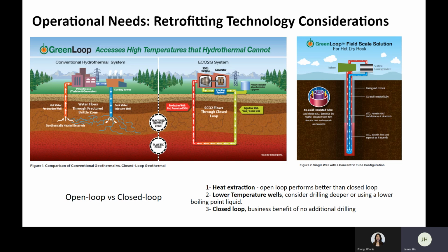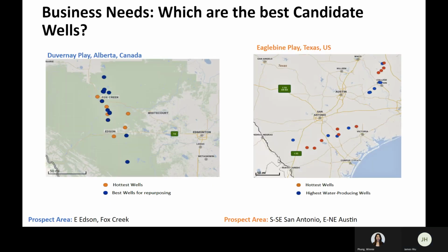And thirdly, we will be generating this heat extraction by pumping colder liquids down the well and using the hotter geothermal heated liquid coming up from the well to power a turbine. Therefore, if the selected site is not sufficiently hot, we would need to consider using a lower boiling point liquid, which could add to the expense, compared to water.